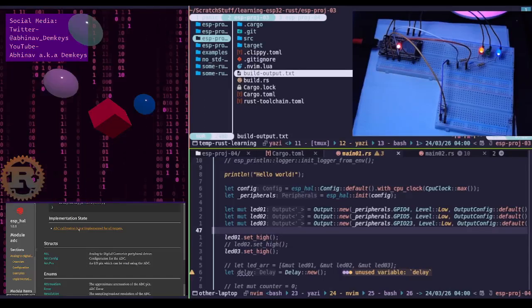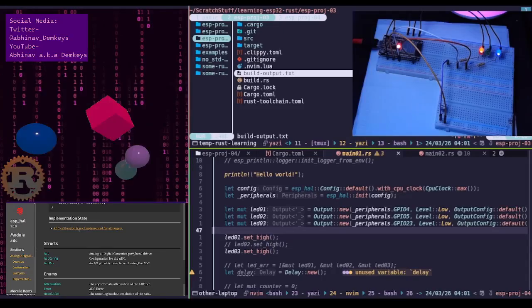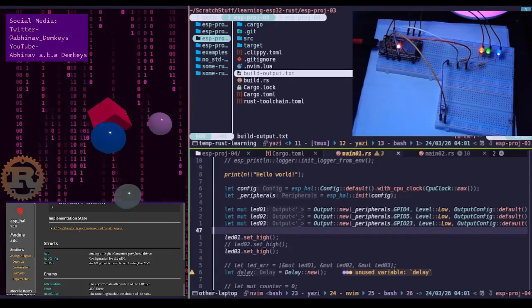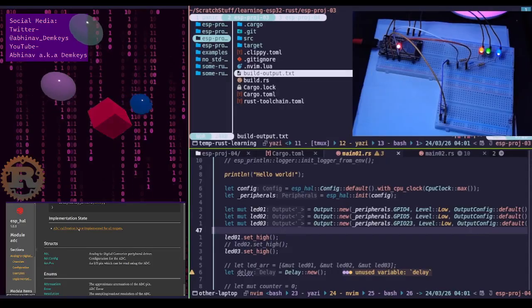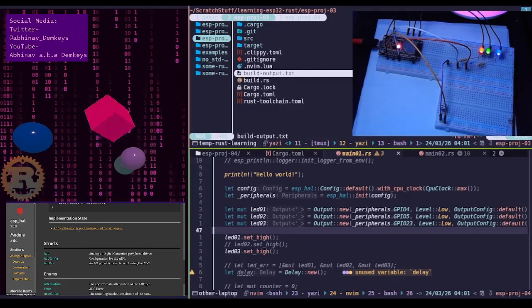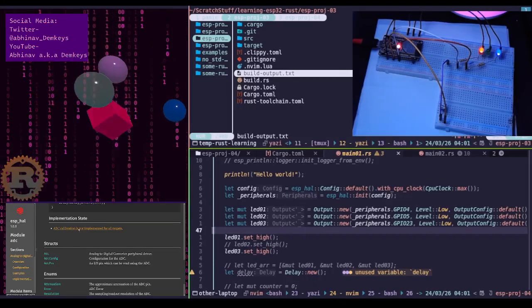The ESP32-specific quirk. The original ESP32, the non-S/C variants, okay, so the one that I'm using, is notorious for having a non-linear ADC response, especially at the very low and very high ends of the voltage range, near 0 volts and near the reference voltage.